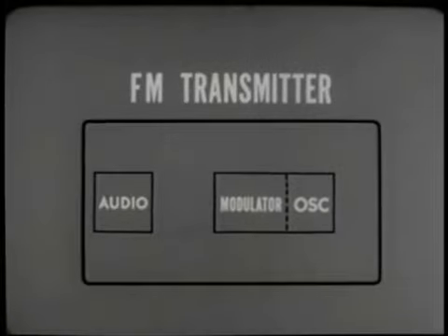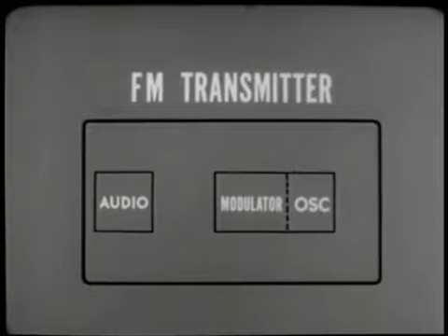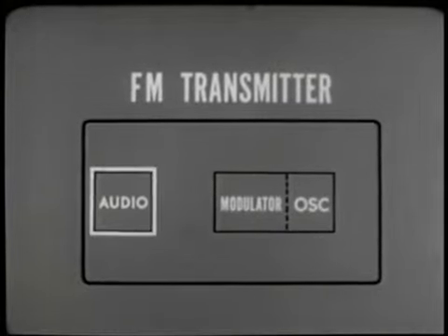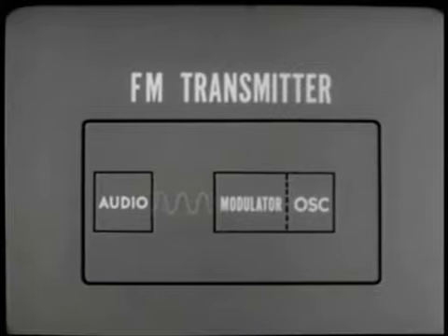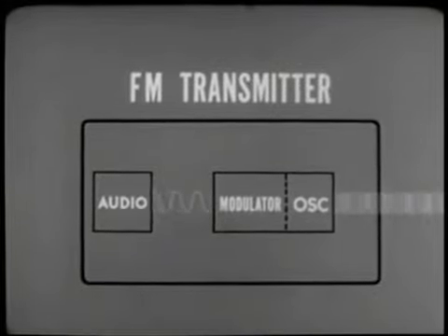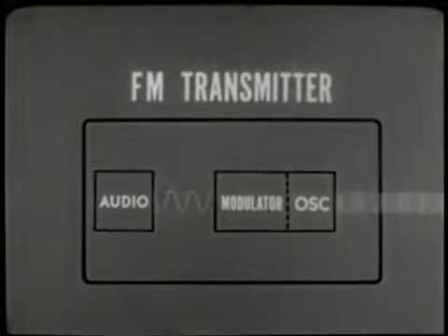Now that we are familiar with the basic principles of FM, let's make a quick rundown of the components that make it possible. The transmitter's components are similar in name to their AM equivalents, and they do similar jobs, but in a different way. The audio circuits provide the audio frequency signal, which is fed to the modulator. The action of the modulator is such that the output of the oscillator is a frequency-modulated RF wave. The components of the FM receiver are a bit more complex, for they have an additional factor to contend with.